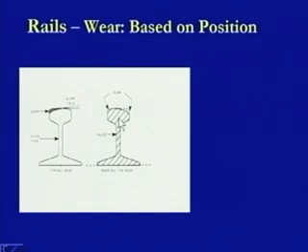This is another case. This is an inner rail section where the gauge face is being provided here, and then this burr is taking place, like this is getting tilted in this direction slowly and slowly. So, what we found is that this is the actual shape which has been there, but there is a deformation in this shape also at this location, and this is a total tilting of this one. So, this is another condition of burr which is taking place, and this may be because of heavy loads which are coming and the striking of those heavy loads at the top surface.